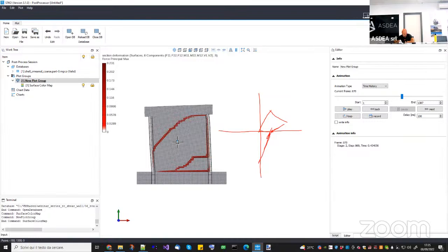Then when I go in compression, let's say I have a certain unloading stiffness, which is not exactly the initial one, can have a certain amount of damage, but when I'm here, I will reload in tension at this place. Now, this seems not important, but actually, if you have a lot of cycles, it can create issues.